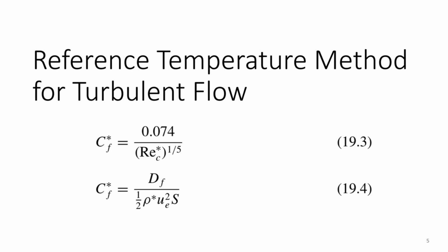And calculating this reference temperature, we approximate the real value of viscosity, and can use this reference viscosity in estimation of friction drag and thickness of the boundary layer.